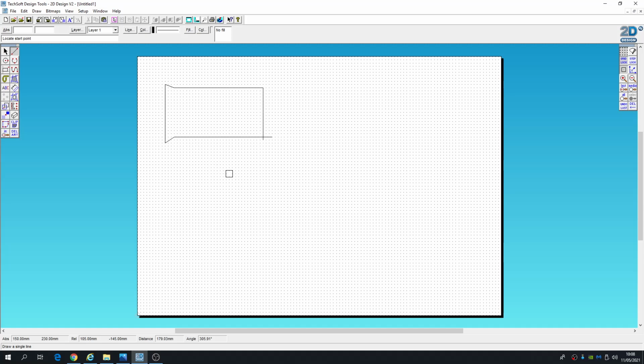Yeah, so you can either attach it, in which case now you could go to delete any, select on the hyphenated one, and you can either join up lines where you literally join end to end, or you can cross them and then delete off the bits you don't want. But I find it easier to actually use a box. But that's what the align tool does. If you were doing a drawing and a line was broken, you can attach two ends together and connect it back up again to make a complete perimeter.